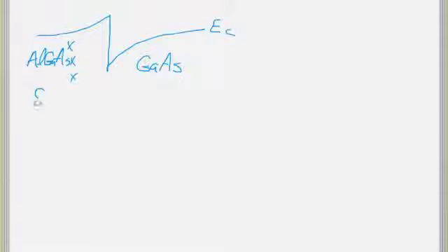The energy level of the dopants is up here, so they will eventually tunnel out. Once they tunnel out, they fall down into this state here, and then they're unable to get back. So you have the electrons separated from the dopants by several microns.